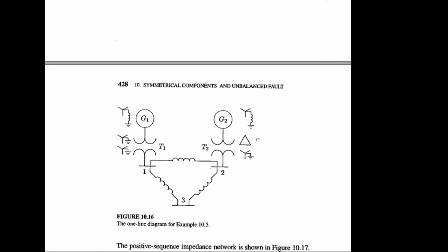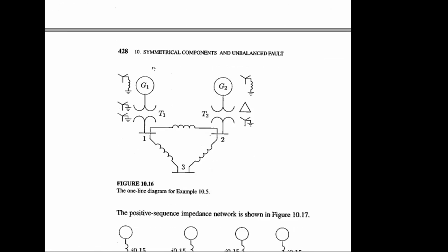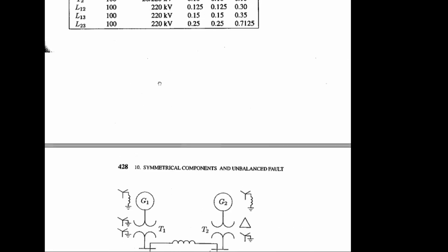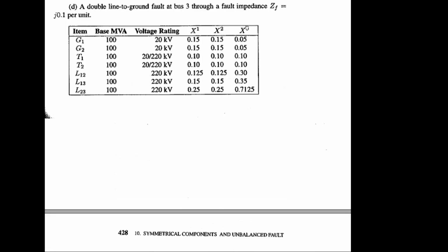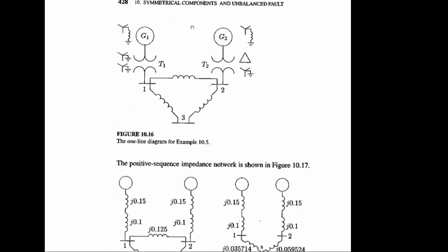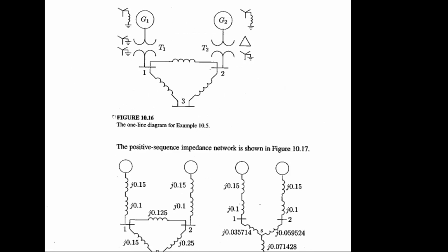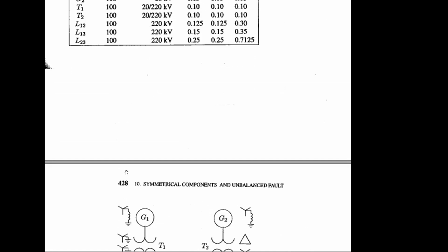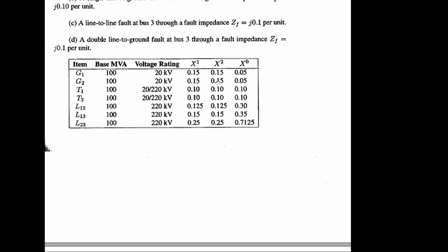First of all, you have to draw the positive sequence circuit of this single line diagram. How can you draw that? You have to replace all the information with its equivalent. Which information do you have to put as reactance? You can put the reactance equivalent of the generator, right? Generator 1 has a reactance equivalent, but you have three reactance values for the generator.